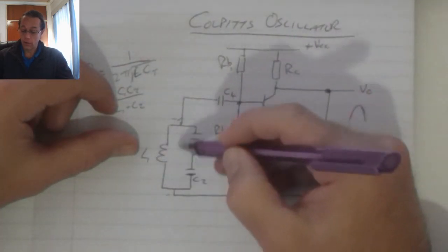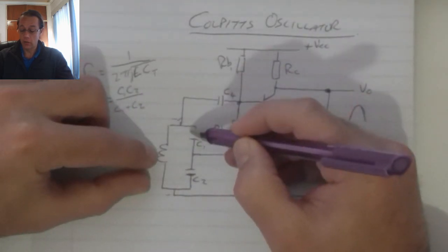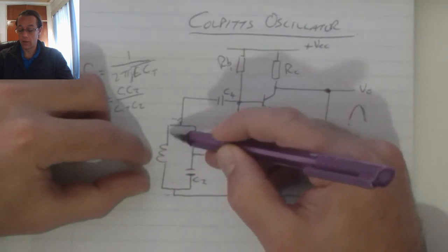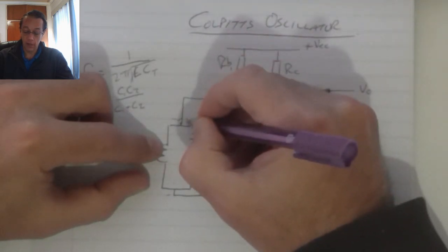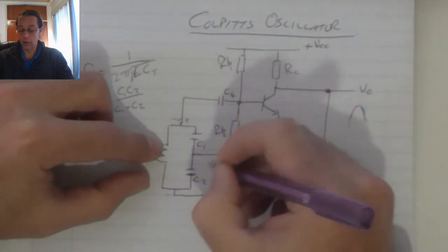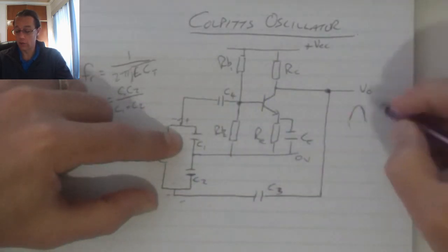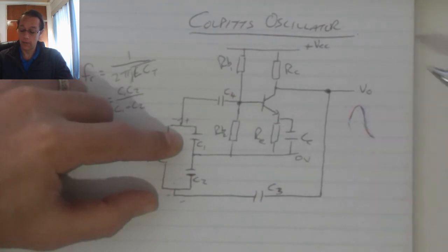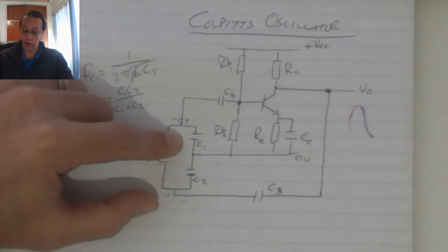Because of that decrease in reverse voltage, the inductor will charge this capacitor due to the back EMF, causing a positive there, and this side to become more negative. That positive turns this transistor more on, which in turn sends it into the negative half cycle. That feedback signal will continue until the saturation is reached.